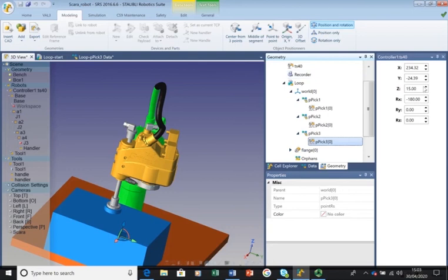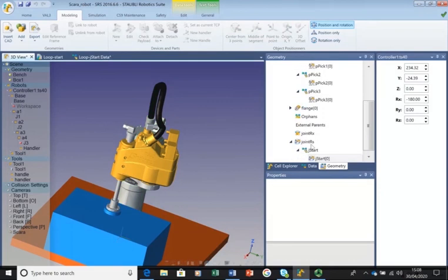Let's just move this up a little bit for the robot home position. Just scroll down. Okay, come down to the bottom here and find J start, and this is just a location that is a safe place. I'm just going to put it just above point 3, so we'll just type in 80 there, so it's just above there, and I'm happy with that.